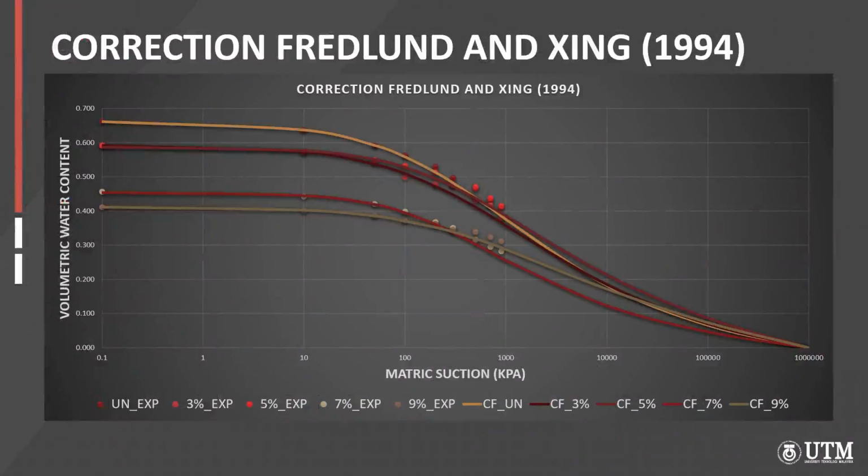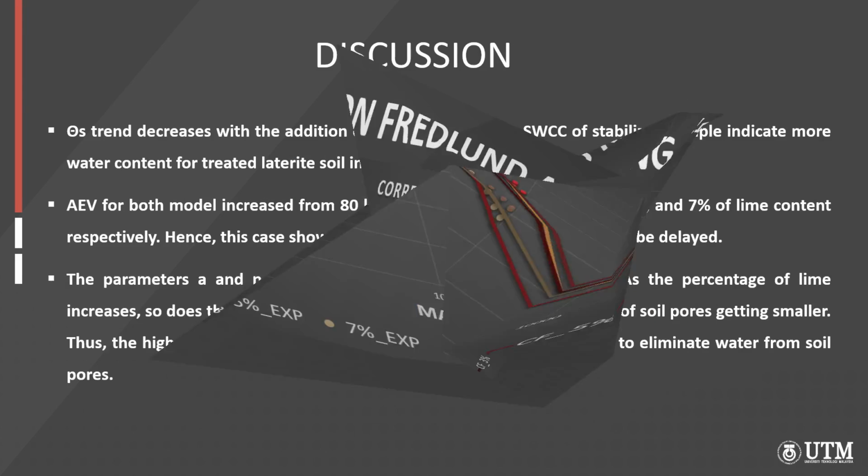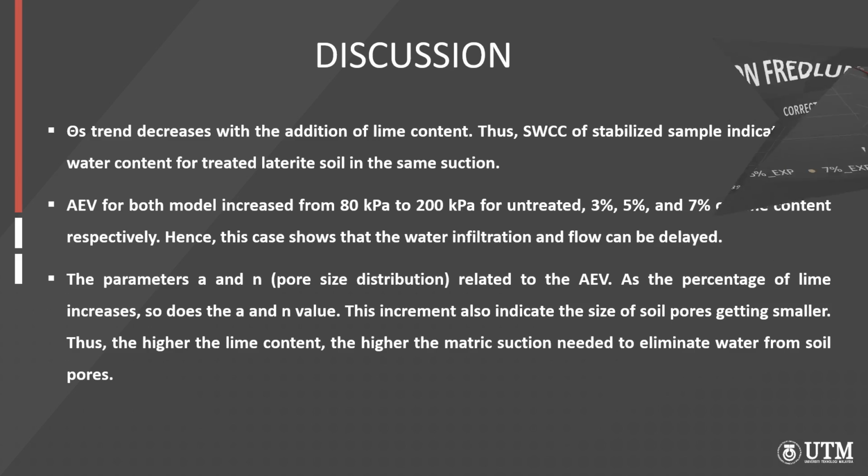Next is the corrected or modified Fredlund and Xing 1994 fitting. This is the log graph that shows the modified Fredlund and Xing 1994. Theta s, or saturated volumetric water content, trend decreases with the addition of lime content.